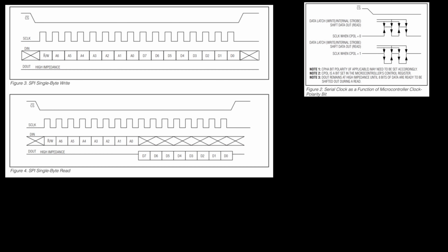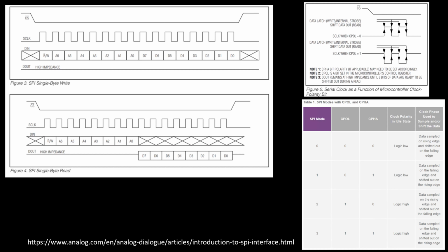Well, something interesting and maybe a little bit annoying as I was working with this device, this is in the datasheet also, and it talks about these are the 2 acceptable ways to communicate with it. So I pull CS low, and then I can either go with this CPOL equals 0 or CPOL equals 1. And as a reminder, there's 4 types of modes for SPI communication. So there's a mode 0, 1, 2, and 3. And as I go through and look at the documentation for this real-time clock, they're essentially listing only modes 1 and 2 are supported. And all the previous SPI work I've done with the rest of my SPI devices have pretty much been SPI mode 0, I believe.